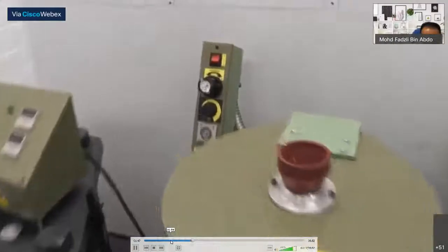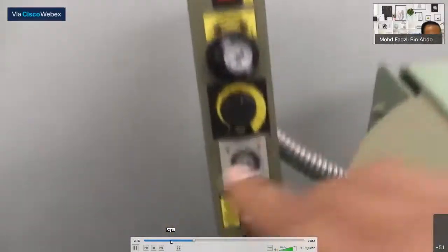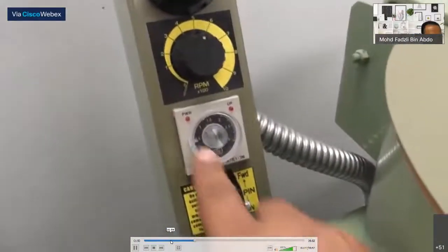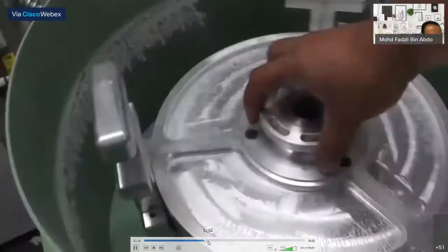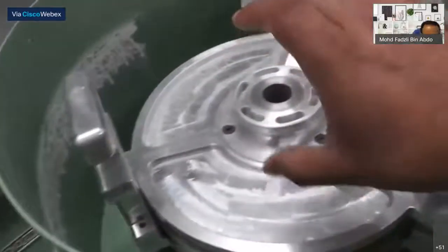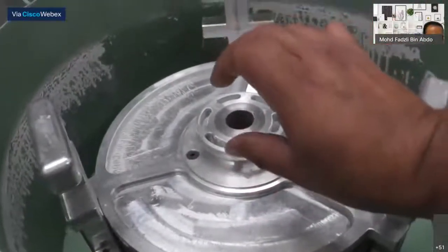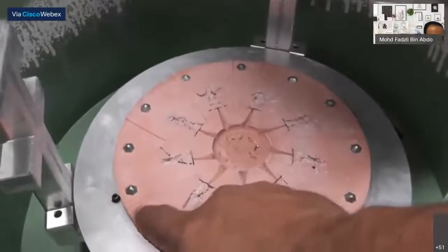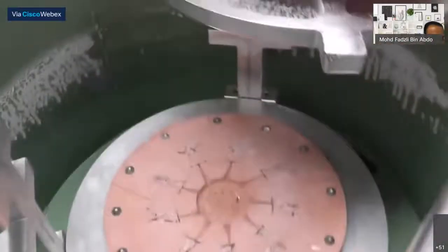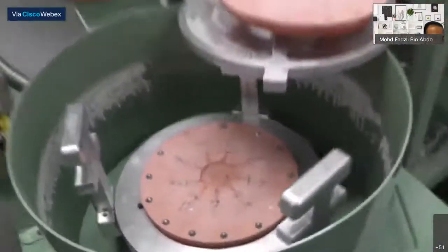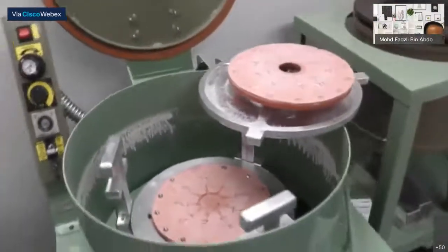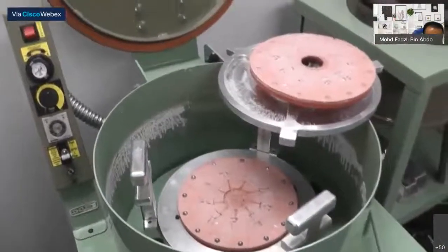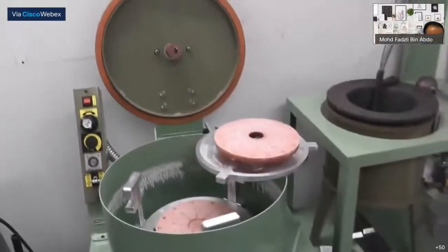So then the spin caster, this has several settings on it. How long the mould spins for, anywhere up to 3 minutes. The pressure dictates this locking plate locks in place, and the pressure in between the mould is relevant in terms of these little gates and the vents and stuff. And if the pressure is too much, the vents get squashed and your figures get sort of, what's the word? Squished, not correctly. So I'm going to spin this mould a couple of times and we'll have a look at the figures that come out.